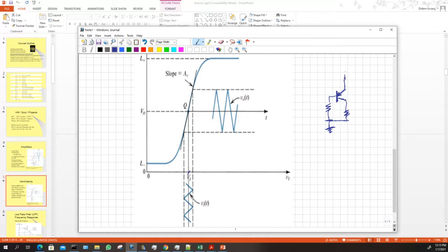And this one is usually connected to, you just throw a little button there and call that VCC. Okay, so this is, actually here it would be VEE, since I have drawn a common collector, I think is what I've drawn here. And then you have a resistance here as well, because you never want to connect any end of the transistor directly to your source, if at all possible. The reason is that you don't know anything about the source.